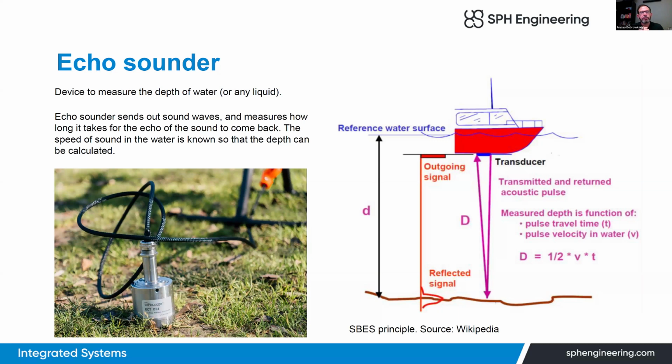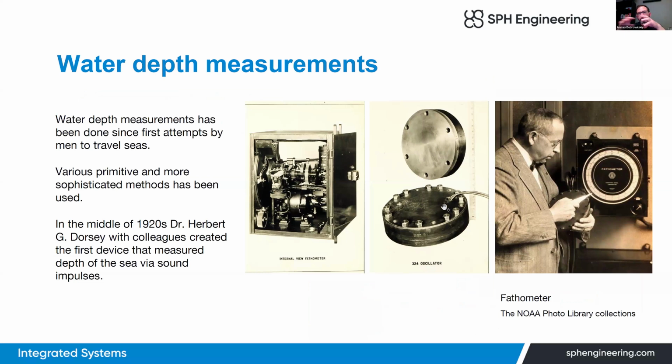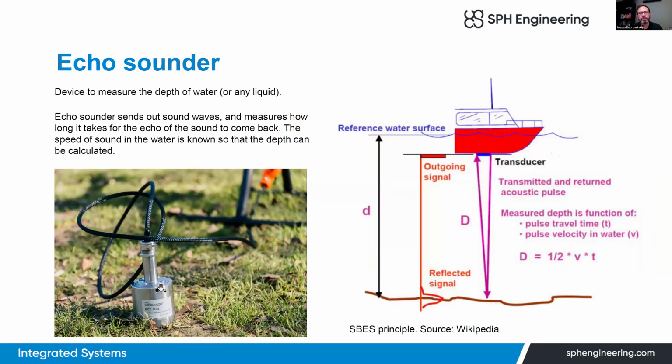And the second big change in technology is digital signal processing. 100 years ago, the echosounder system had many bulky components: a transducer, which emits and after that receives the sound, and also a big analog machine to recalculate time to depth. And now everything is inside the echosounder. It has a digital interface and outputs depth measurements, ready to use.